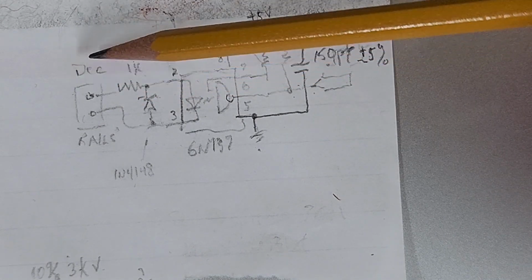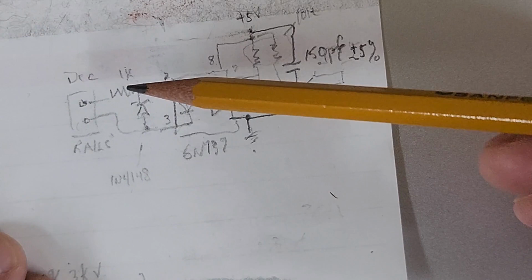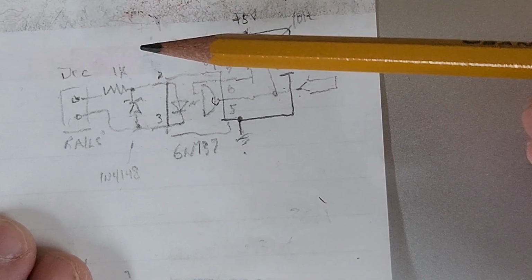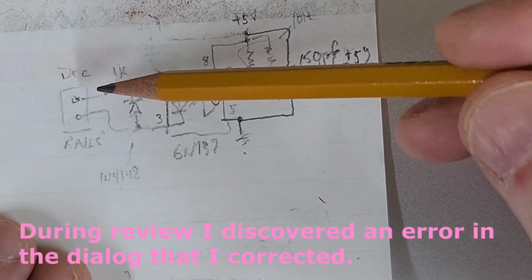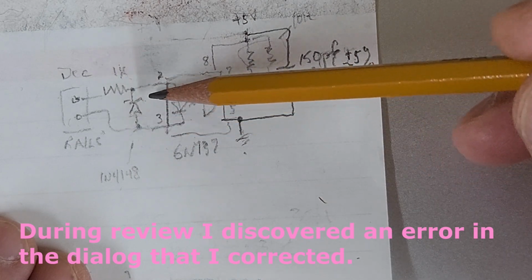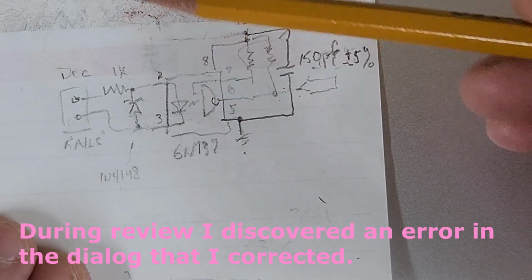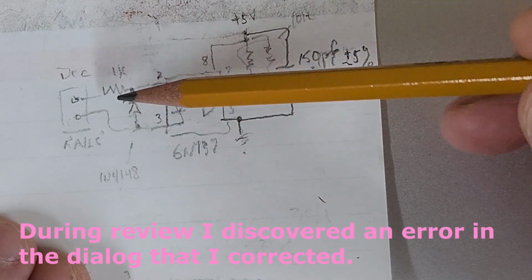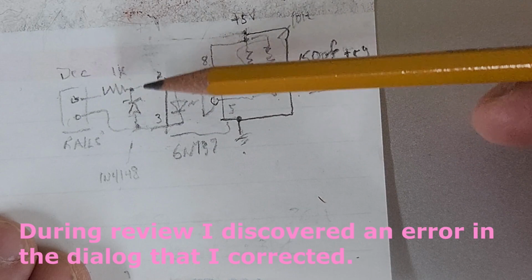The DCC signal coming in, as I stated, is an AC square wave. So the first thing I need to do is clip that square wave, because I'm only interested in the upper half cycle of every one of the square waves. And so what you see here are these 2 diodes. This diode is the reverse diode, and there's one inside the optocoupler right there. Basically what that does is it makes the AC square wave see this 1K resistor as a simple load, but the diode in the optocoupler is only passing the upper half of the square wave.